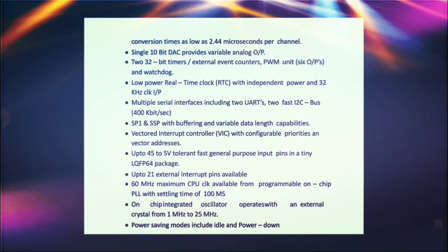Up to 45 5-volt tolerant fast general purpose input pins in a tiny LQFP64 package. Up to 21 external interrupt pins available. 60 MHz maximum CPU clock available from programmable on-chip PLL with settling time of 100 microseconds. On-chip integrated oscillator operates with an external crystal from 1 MHz to 25 MHz.